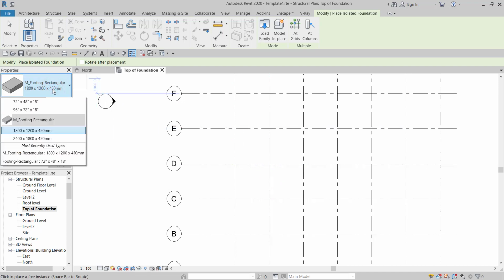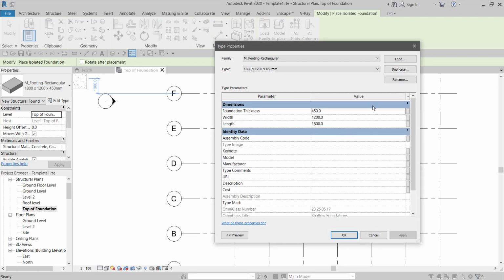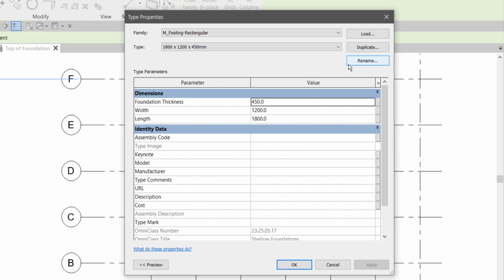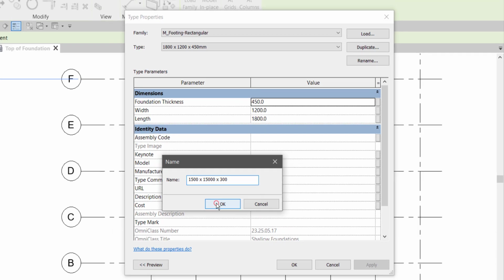So we can also change, edit, or duplicate some of the column bases which we want. So with this, I'm going to do a duplicate here, and I'm going to change this column base to 300 and do here as 500, and also provide here as 500.